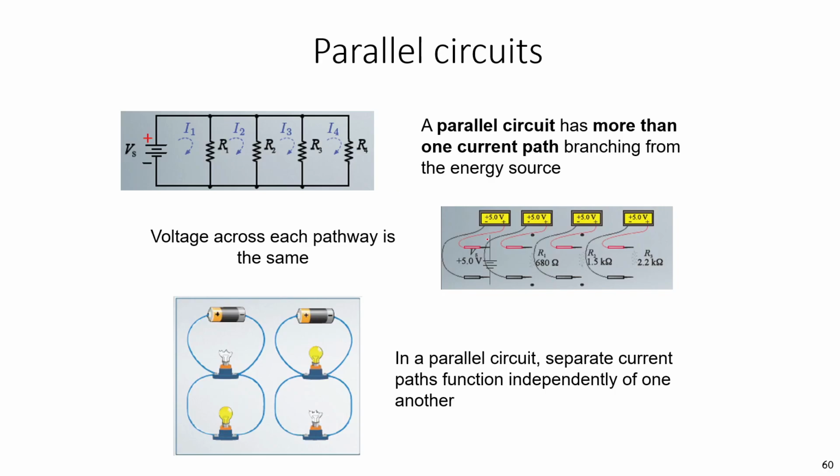But for a parallel circuit, if we connect the lamps in parallel and one lamp is broken, another lamp can still work, right? So usually in the electrical system, we connect the circuit in parallel. We parallel this lamp to this device, to different devices, from the receptacle, right? From the system, it comes like this.